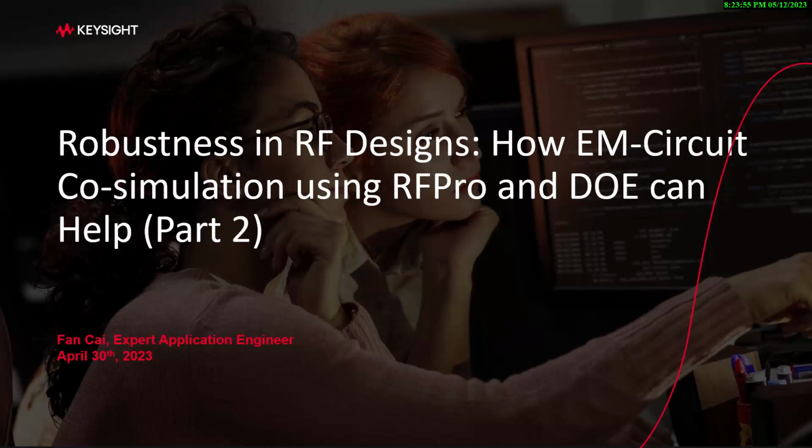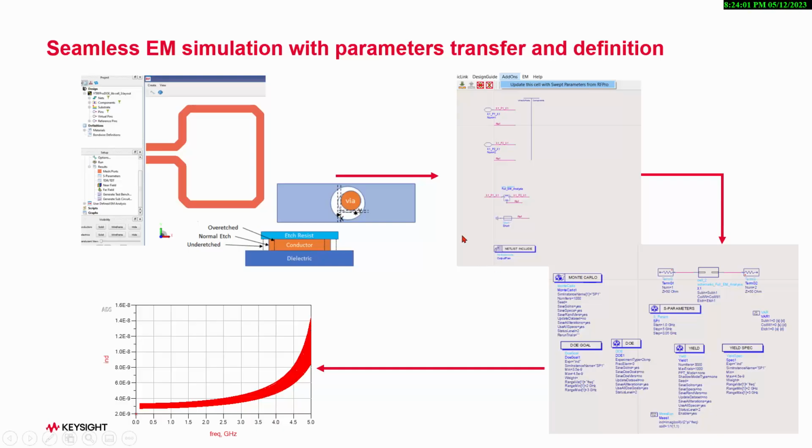A design may work well with its nominal component values, but when you run a yield analysis with multiple dimensions of manufacturing tolerances, such as the substrate height or layout geometry, you may notice a significant variation in your results. This can lead to failures and low yield.